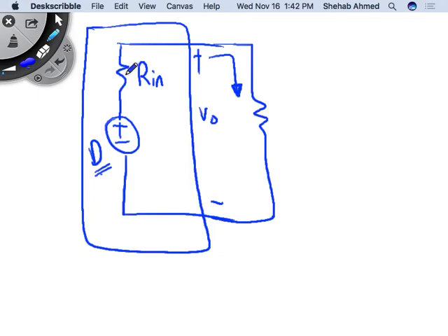So any voltage source, any synchronous machine, a battery, a power converter, any device, can be modeled. In power systems, in 459, how are we modeling synchronous machines? An ideal voltage source with a reactance in series, because there it's AC, so we have to include the reactance. We can put a resistance as well, but here it's DC, so there's no such thing as reactance here. So it's only resistance here.